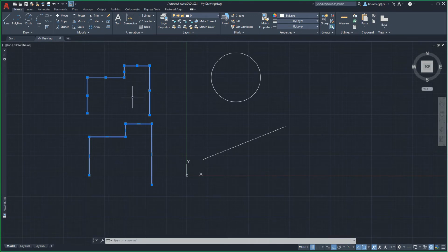Left-click on the midpoint of one of the line segments. This midpoint will turn red, and if you glance at the command line, you will see that the software has automatically entered the stretch command and is requesting the user to specify where in model space the user wishes to stretch or relocate this chosen line segment. Move your cursor to relocate the line segment, and then left-click at the point in model space desired to place this relocated line.